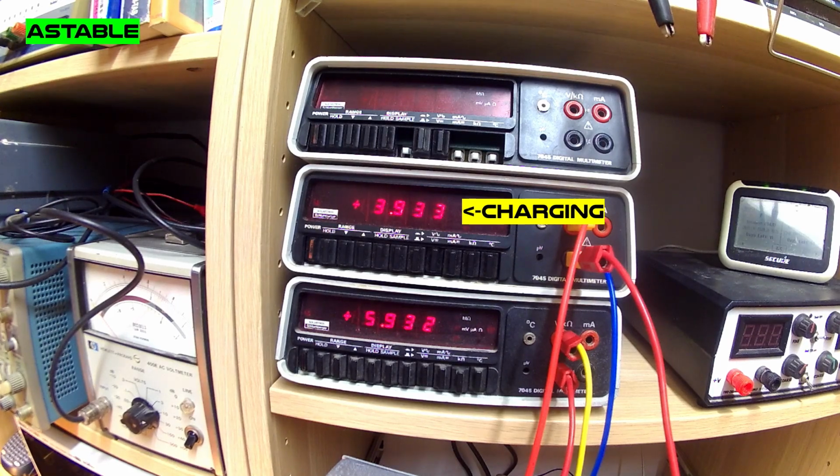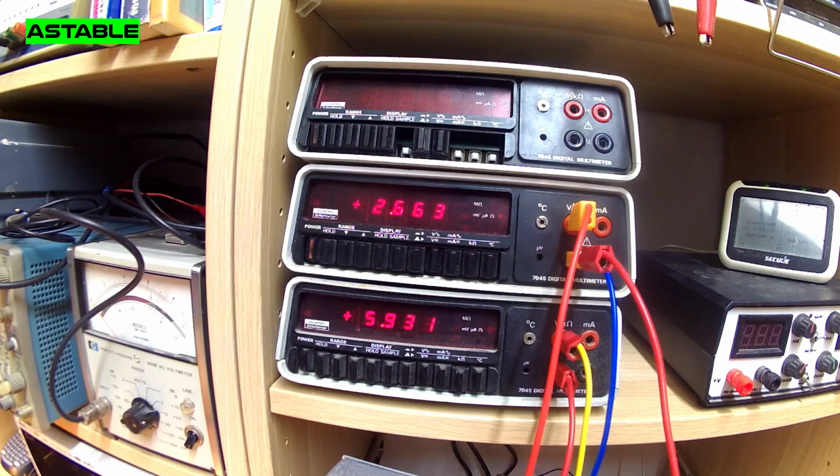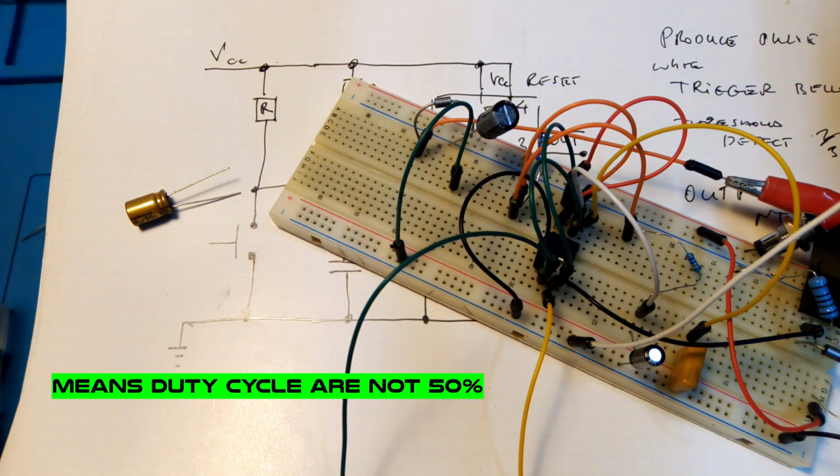Of course, the first pulse is always longer because we charge from 0 to 2/3. The next pulses are shorter because we charge from 1/3 to 2/3 of VCC. They are not equal because to do that we have to calculate the two resistors more carefully.